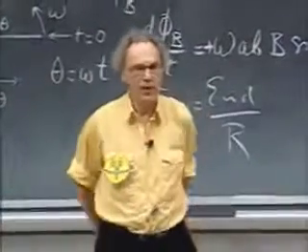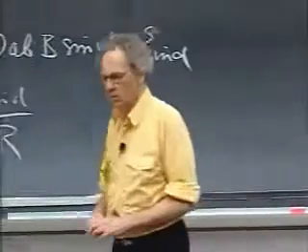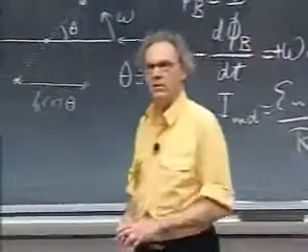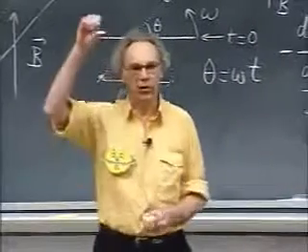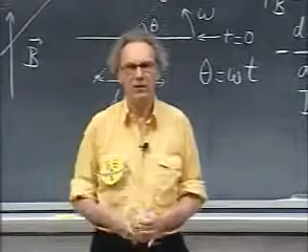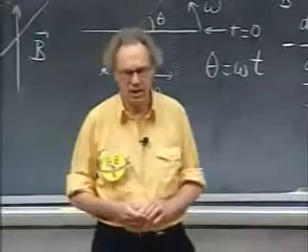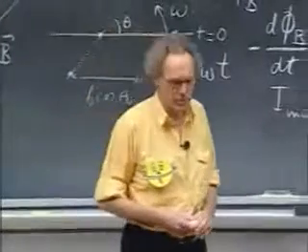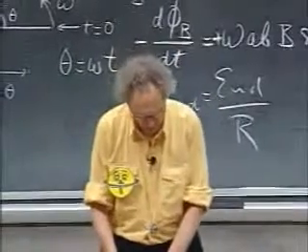And perhaps you remember that I did a demonstration with the winning motor. I blocked the rotor, and I showed you that the current through the rotor, when it was blocked, when omega was 0, was 1.6 amperes. Simply Ohm's law: battery voltage V, resistance R, the current is V divided by R. Then we ran the motor, and the current went down enormously, by a factor of 40. It was only 40 milliamperes, the time average current, when the motor was running. The reason is what you see here. You get an induced EMF, an induced current, which opposes the current from the battery.